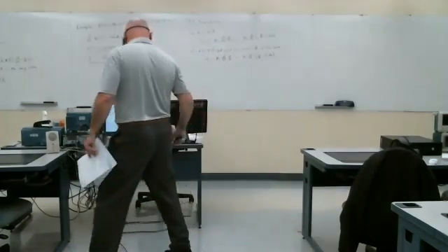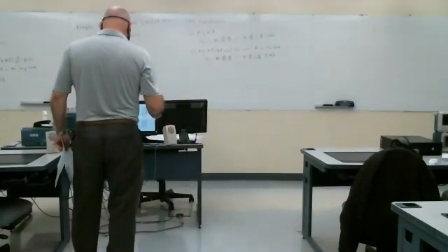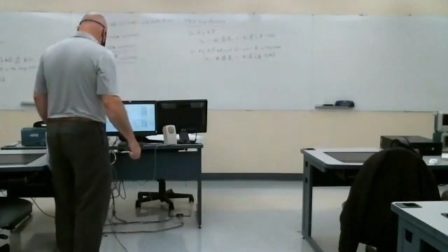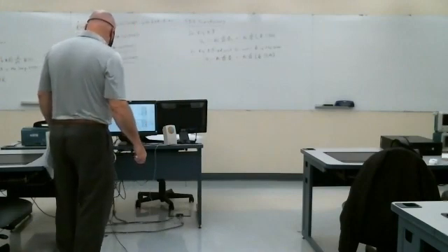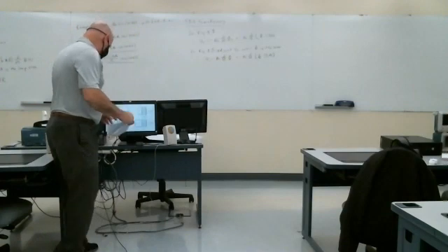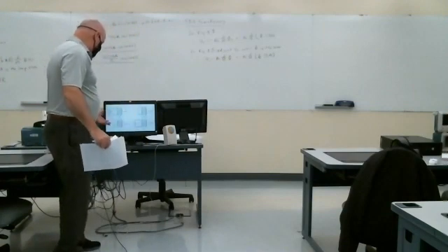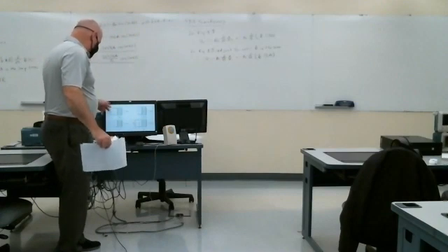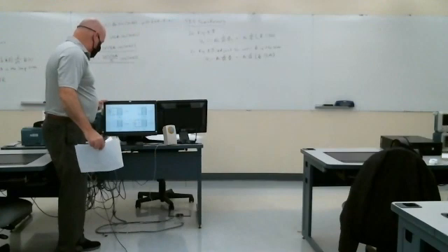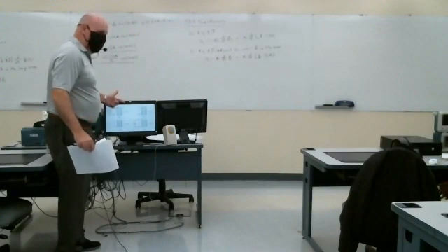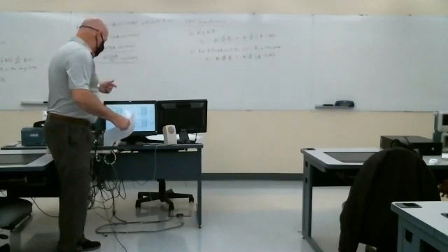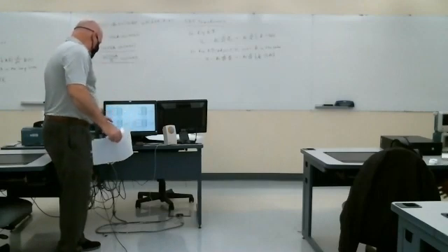And so in that case, I said this wrong previously. So in figure 8.6, the top coil is a load, so current flows into the plus terminal, and the B field would be minus Z directed.